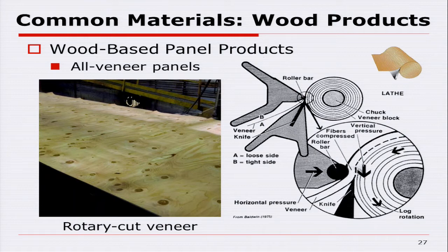It's thrown away. The other thing is you can only peel so far into the center. And we don't necessarily want the center of the wood either. That's what we call juvenile wood. It has very different properties. At least we don't want one veneer that's solid out of the center. So we don't use the center. That typically gets used for fence posts. That's what fence posts really are if you go to the store. They're the center of a log that's typically been peeled.